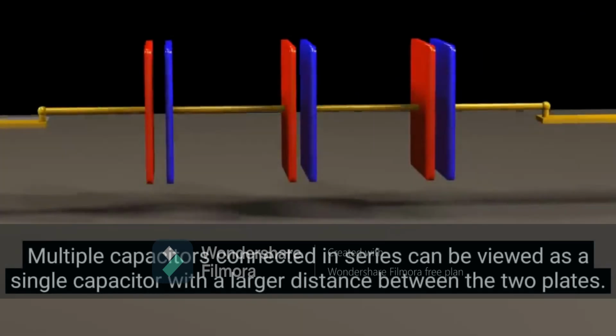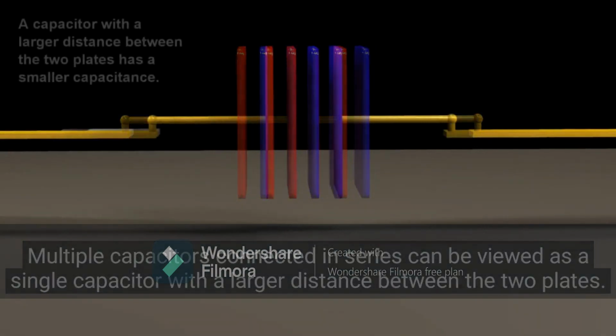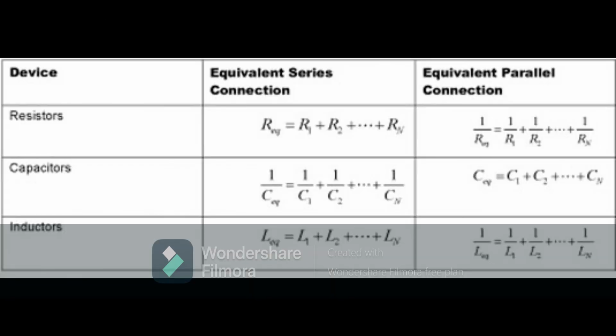Again bringing them closer and making it one capacitor, the distance between the two plates becomes larger. We have seen earlier that if the distance increases, the capacitance value decreases. So if capacitors are connected in series, your capacitance value decreases. If they are connected in parallel, your capacitance value increases.